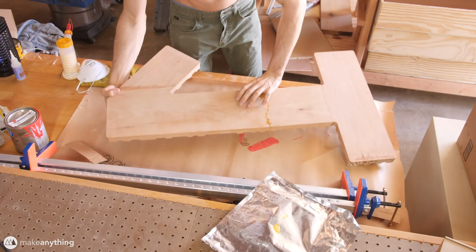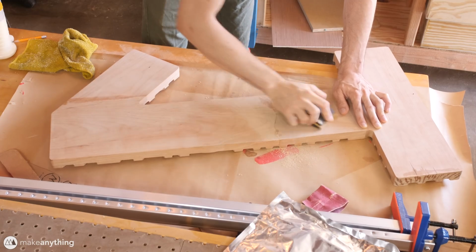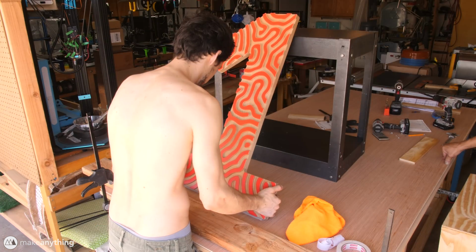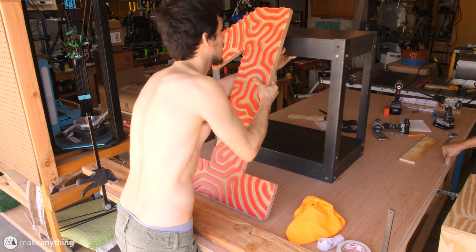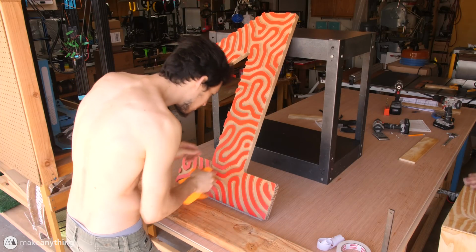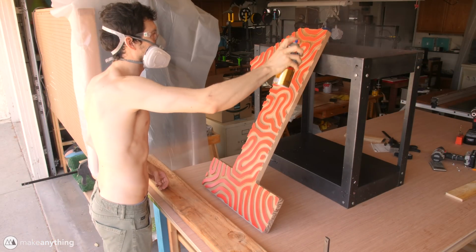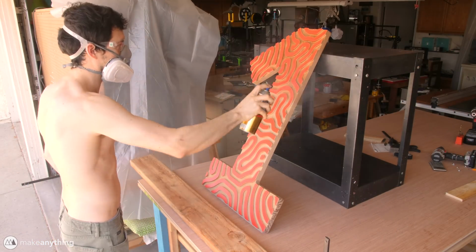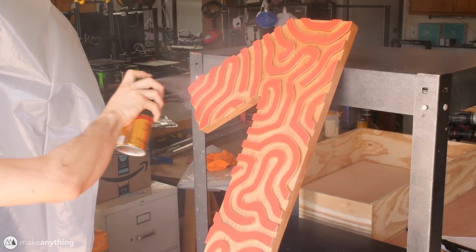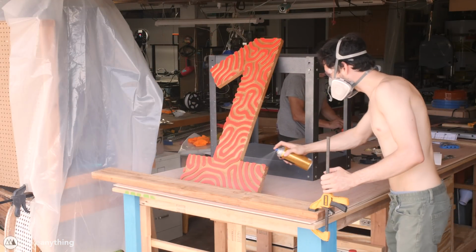Now I'll just flip it over and scrape off some of that excess glue, sand it flat, and now we can do our final coats of polyurethane. So I'll set my number upright. I put a little bit of double stick tape on the bottom edge just to make sure it doesn't slip away. And then I'll go ahead and do several passes with this polyurethane spray. The spray can works a lot better when it's upright, so that's why I have it standing up. And I think I did 5 coats with 15 minutes between each coat.